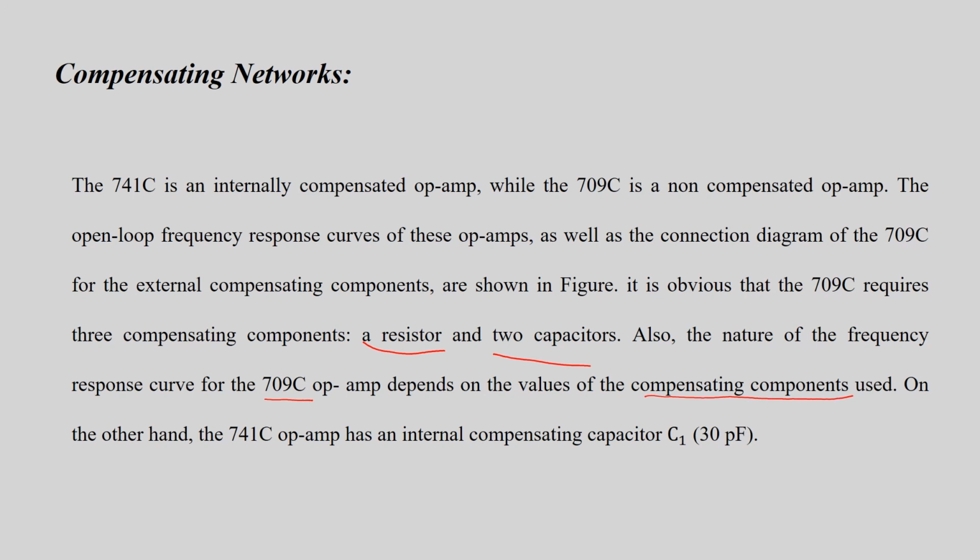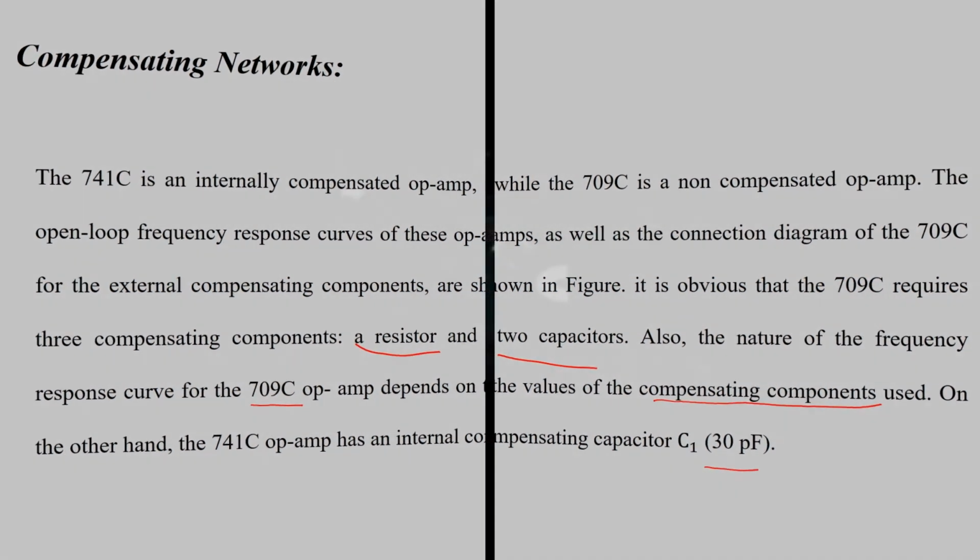On the other hand, the 741C OpAmp has an internal compensation capacitor of 30 picofarad. Next class we will be talking of frequency response of these internally compensated as well as non-compensated or externally compensated OpAmps.